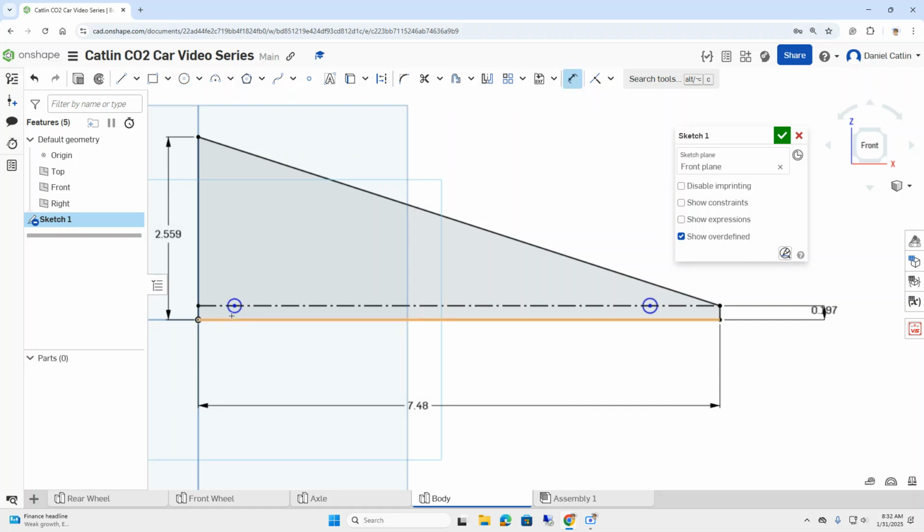I'm going to dimension the distance that this is from the side. Okay. It has to be 15 millimeters or closer. So I'm just going to go ahead and do the minimum that it could be. It could go further in on both of these sides, but I'm just going to set that constraint up for now. I think they can be within 15 millimeters from the edge, but they have to be a certain distance apart. You can look at your constraints for that. Okay. So those are the holes.